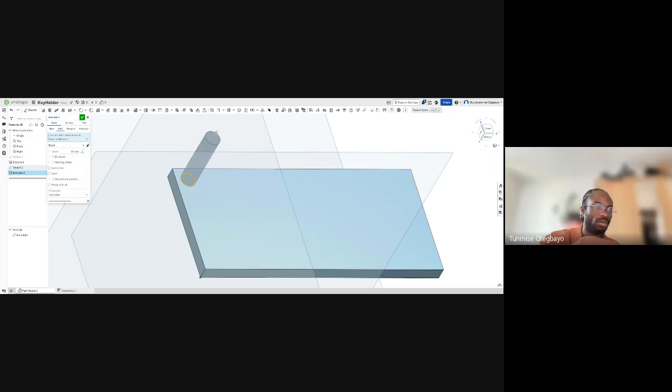It's just another thing that we have pulled up on top of this rectangle. This doesn't look right, so we have to go back to our extrude tool and look. You can see that there's a menu here that says new, add, remove, intersect, and this basically tells the extrude what type of thing you want to do.